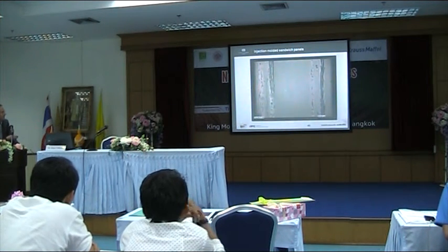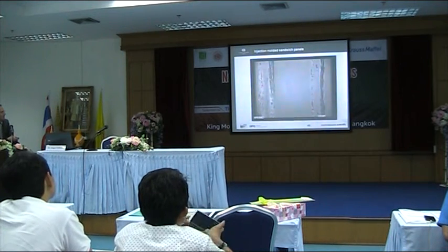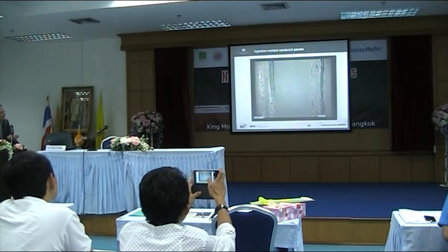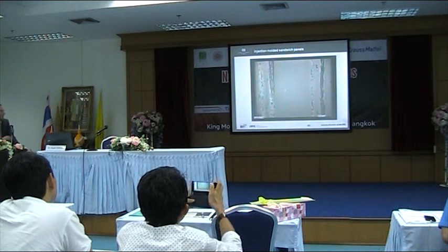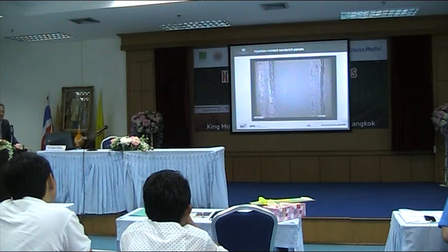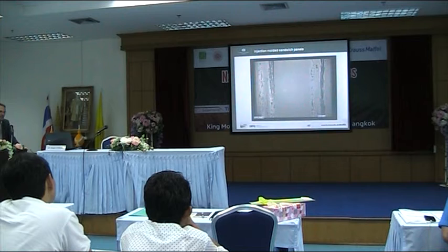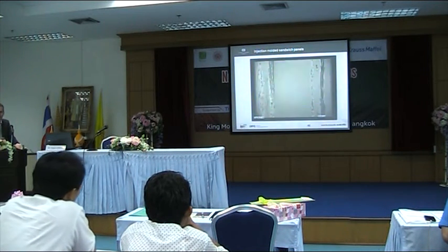You see it here in a polished micrograph. You see the fibers, with fiber orientation of 0 and 90 degrees in the top layers. In between we inject the melt. So this is something you can locally reinforce in an injection molded part with textile reinforcement. Not only short fiber reinforcement, but integrating textile reinforcement into the mold to make parts with endless fibers in the injection molding process.